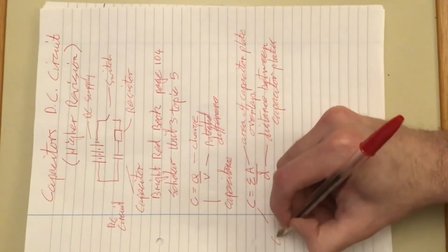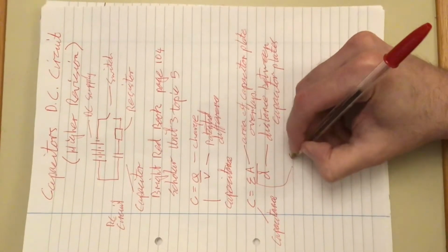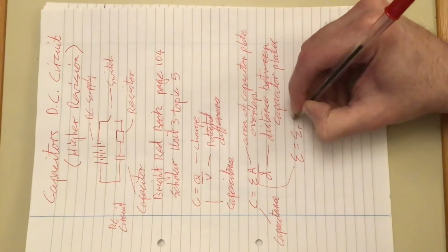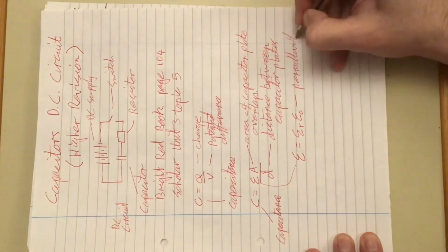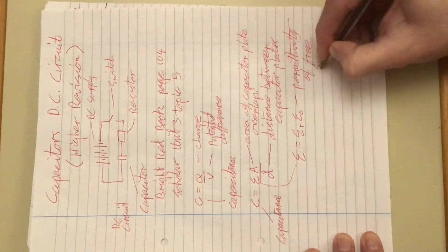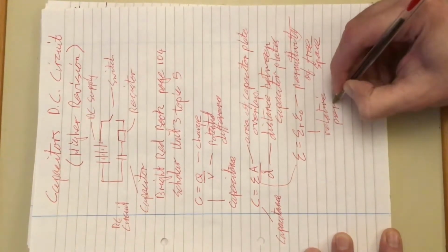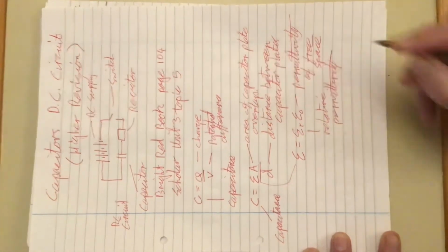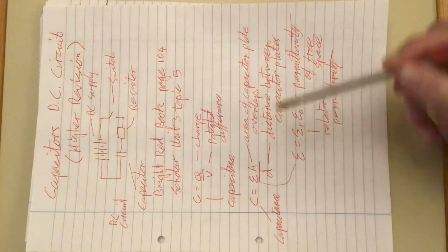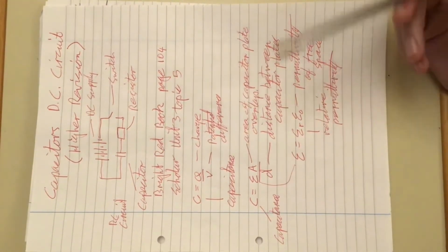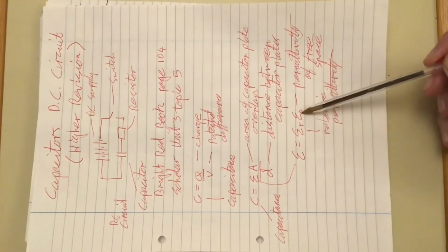C is, of course, the capacitance, again. And epsilon, well, you should already be used to the idea that epsilon is the permittivity, because you should be well and truly familiar with epsilon naught, the permittivity of free space. Epsilon R is the relative permittivity. Now, why on earth do we have a thing called the relative permittivity? That is because this gives us a value that allows for what material is between the two capacitor plates. If it's an air-filled capacitor, which is to say one where it's just air between the two capacitor plates, then epsilon R is so close to 1, we might as well just say that it is 1. In other words, we'd use the permittivity of free space.